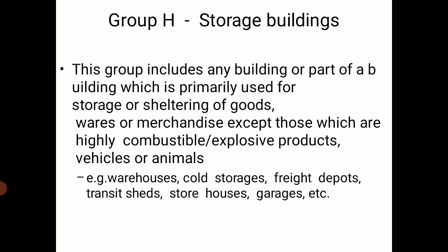Then group H is storage building, that is a building or part of a building that is meant for the storage and sheltering of goods, okay, or merchandise, vehicle, or animal. So examples of such buildings include warehouses, cold storages, transit sheds, then garages, hangars, etc.